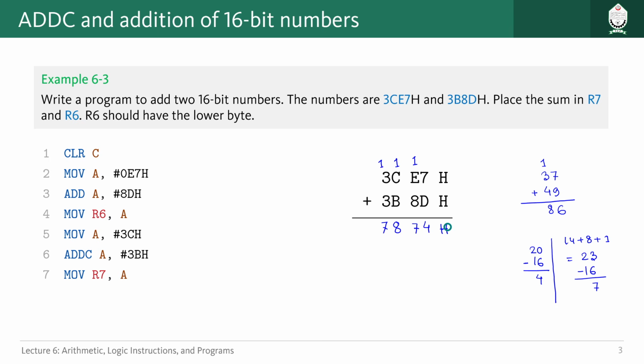Now what you have to understand, each time we can just calculate or add two 8-bit numbers in 8051. This is 16-bit, so what we have to do, first of all we have to add these two numbers, then we can move on to the next stage, right? This is how it will work. So you see, whenever we go to the next stage, if there is any carry from this stage after calculation, that should be considered for the next stage calculation.